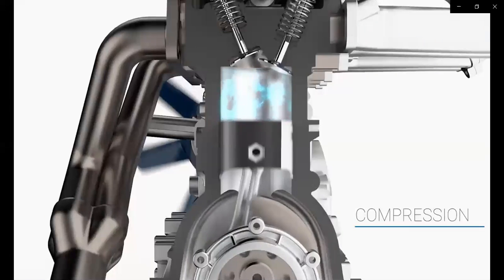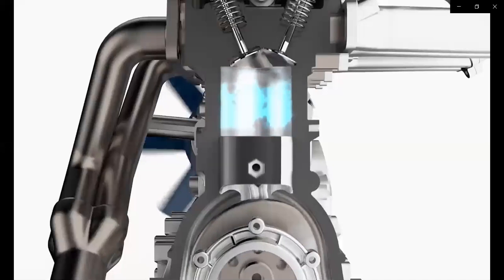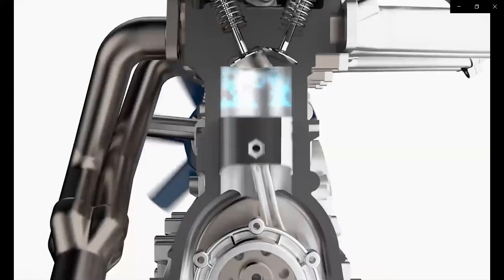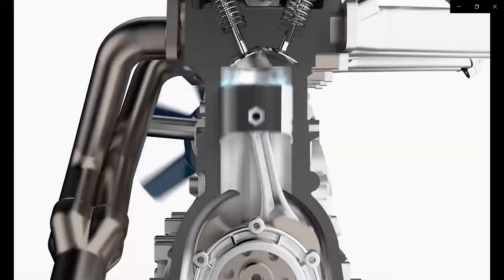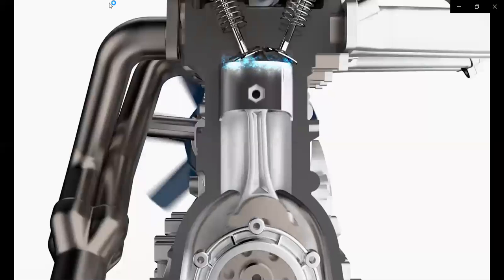Second stroke, compression. During this stage, both the intake and exhaust valves are closed, and the piston moves up the chamber to the top. This causes the compression of the fuel-air mixture, which decreases to one tenth of its volume. At this point, pressure rises drastically as the air and fuel molecules are compressed together, colliding with each other and increasing the temperature. Now we are ready for the explosion.